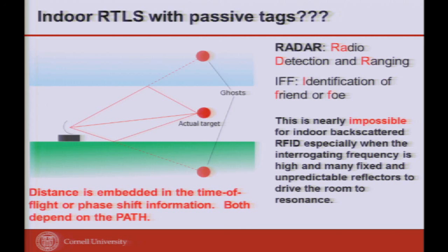Just how do you adapt this to indoors, where you have a lot of ghost images? In open space, you have ghost images from the sea level, ground reflections or ionosphere reflections, but they're limited. If you can use an algorithm to figure out what is a ghost and what is a real image, fine. Indoors, there is a lot more multipath, which is difficult to figure out. So reducing multipath is a very important step in locating. Most of the things are figured out, but if you have way too many ghosts, it makes your system easy to fail. If I can reduce the number of ghosts from the reflecting surfaces, you get much better ranging.